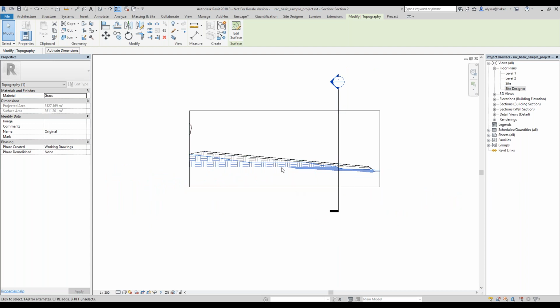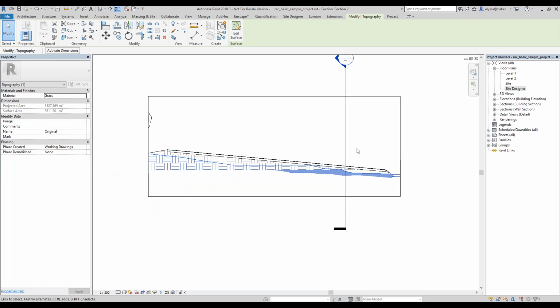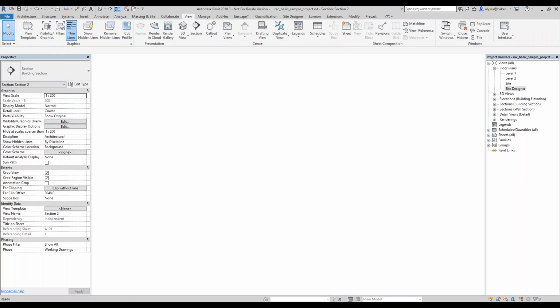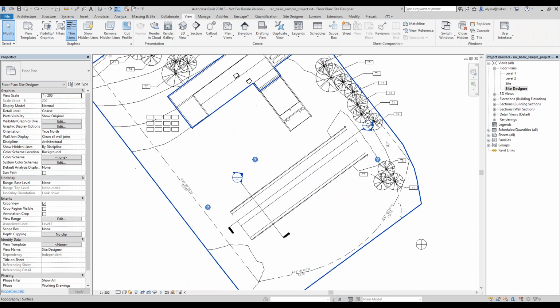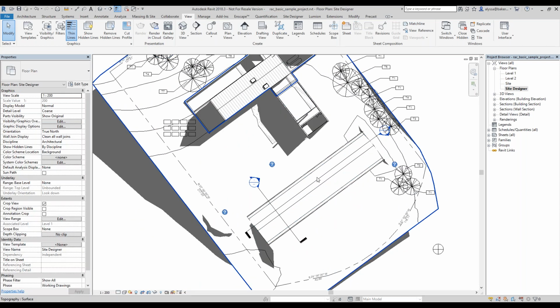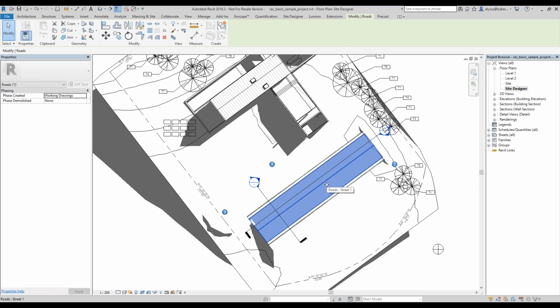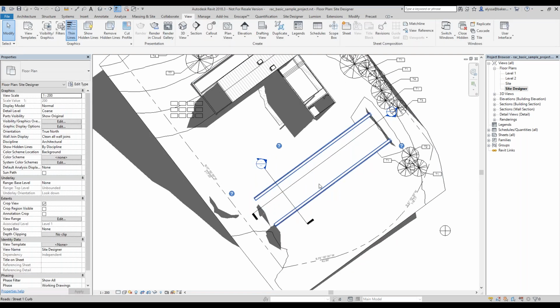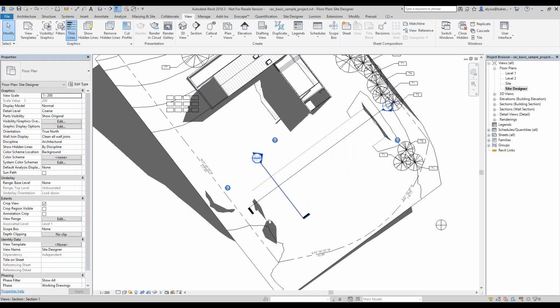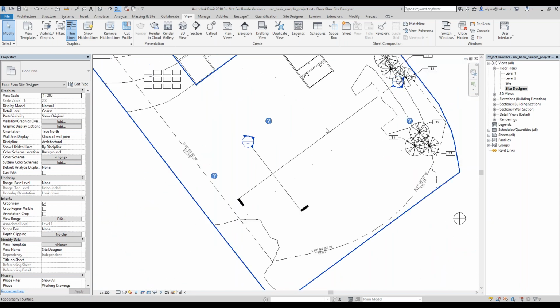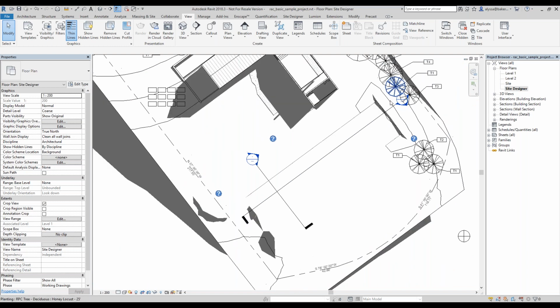So if I had chosen the constant elevation, it would have just done it straight at one level. But we can go and try that out and see what that does. So let's go try that out quickly. What I'm going to do right now is delete this road on here, and let's see if we can fit in doing one more element. You can see that I'm deleting it, but it's staying with this modeled-in topo surface according to what the road was doing.